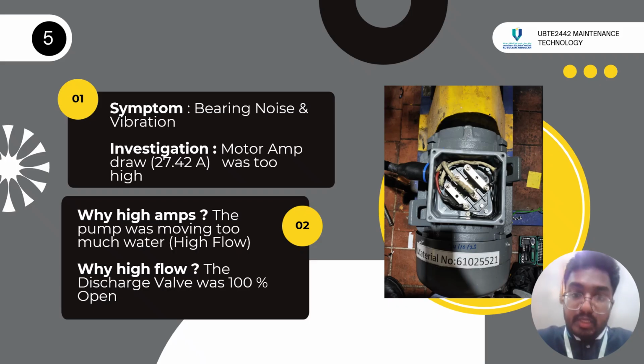Because the discharge was 100% and the motor was running 24/7 without rest, the motor's performance decreased and the grease of the motor decreased, causing a lot of problems, vibration and loud noise coming from the motor.